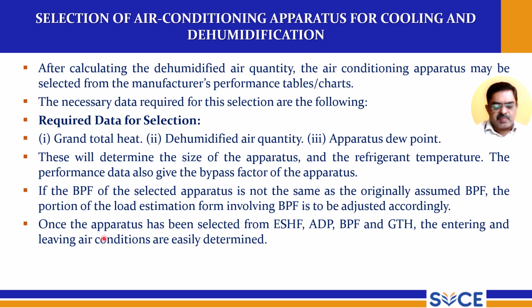Once the apparatus has been selected from ESHF, that is effective sensible heat factor, ADP, that is apparatus dew point, BPF, bypass factor, and grand total heat, the entering and leaving air conditions are easily determined. So once the apparatus is selected from these points, the air conditions will be easily determined.